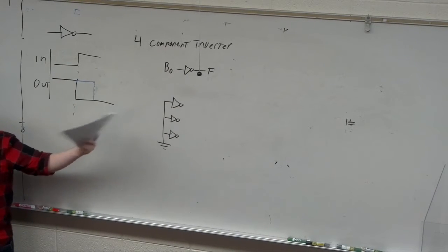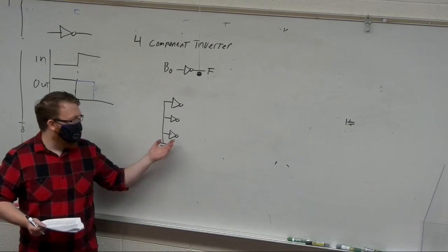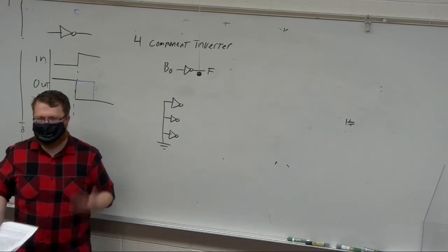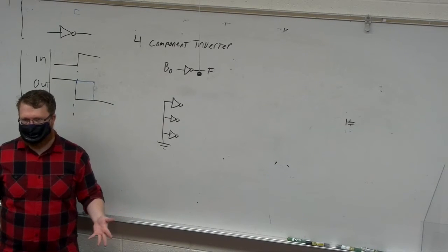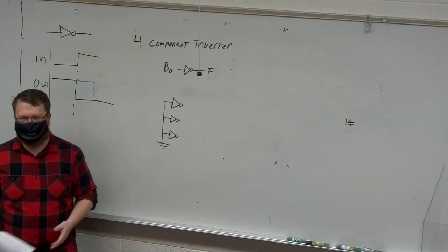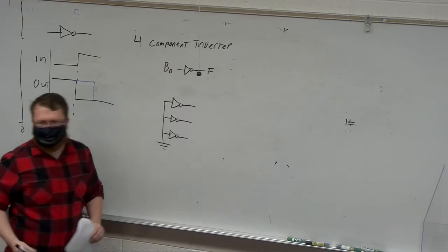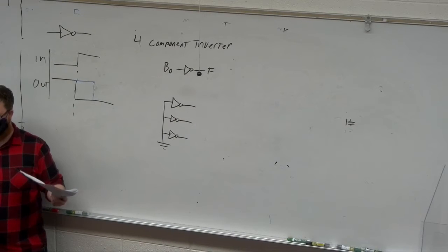It doesn't really matter because your major power consumption is from switching the inputs. That's called the dynamic power consumption. So anytime you're going from low to high, it's dynamic. If it's stagnant, it's your static power consumption. If these guys are staying high or low and have no load, that static power consumption is virtually nothing.